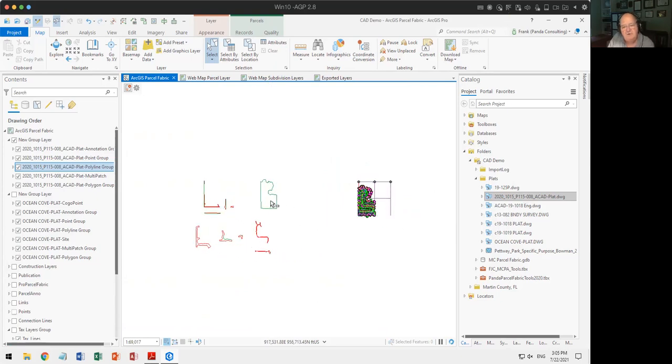And these could have been part of viewports that were in there, because there's paper view and there's world view inside of an AutoCAD. So this could have been for world view, and this could have been for paper views. Maybe they were doing a detail sketch on it. The point is you always want to make sure to look to see whether or not that CAD file has extra lines in there, extra things that are drawn out there that are not needed and are just extra for the drawing files themselves.